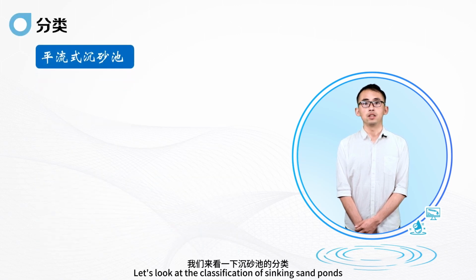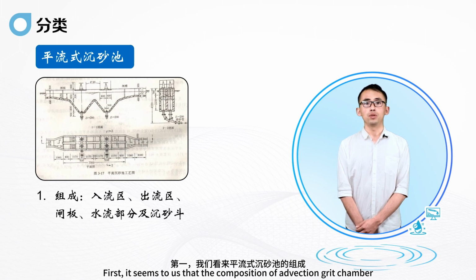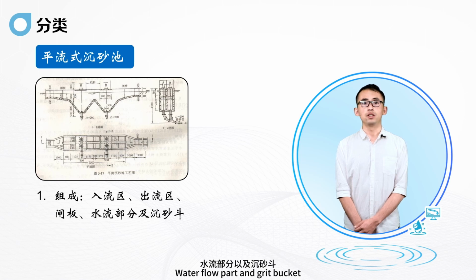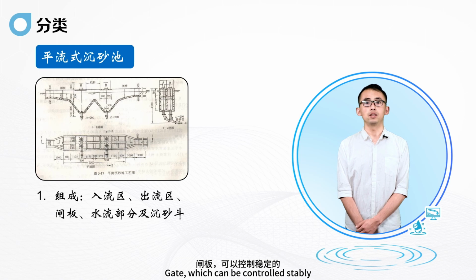Second, let's look at the classification of grit chambers. Let's first take a look at the horizontal grit chamber. It is generally used in relatively large sewage treatment plants. The composition of the advection grit chamber can be divided into the inflow area, outflow area, gate, water flow part and grit bucket. Each part has corresponding functions. In the inflow area, the water flow should be uniform, and in the outflow area, the water flow should be stable. The gate can be controlled stably.